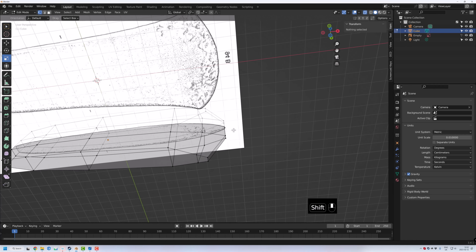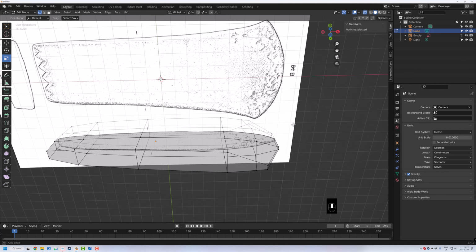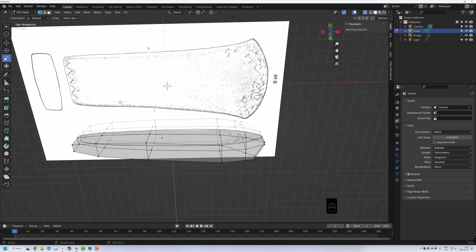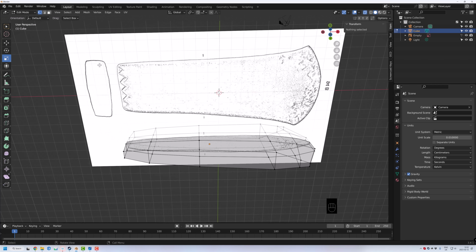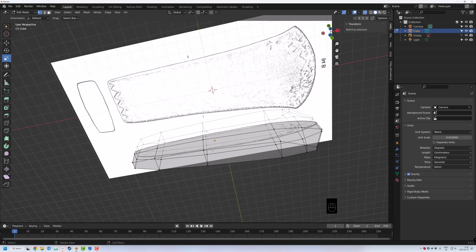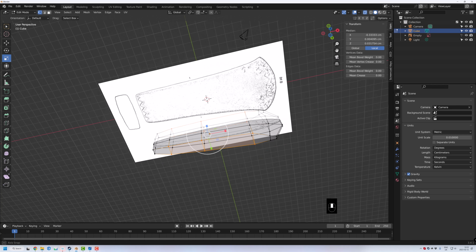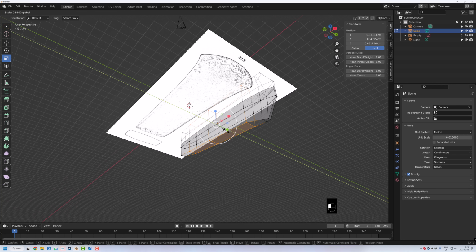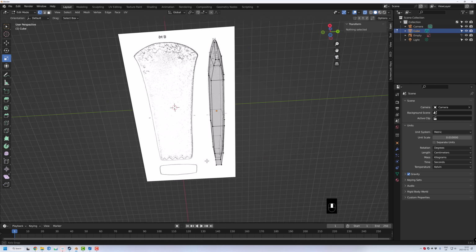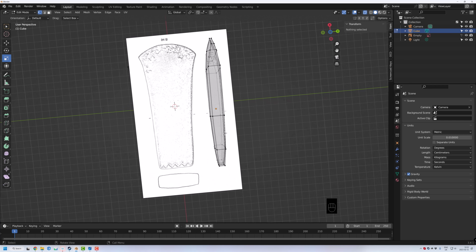Right, so now we have a slightly better shape on the front. Because we can see on the edges that these ones are slightly curved, they're not perfectly square. We should also select the ones on the edges. So I'm holding Shift, and then I can just click the ones that I want to add to the selection. If I add one that I don't want to select, I can press Control and deselect it. And let's just scale them down just a touch. Right, so now I'm quite happy with that shape.